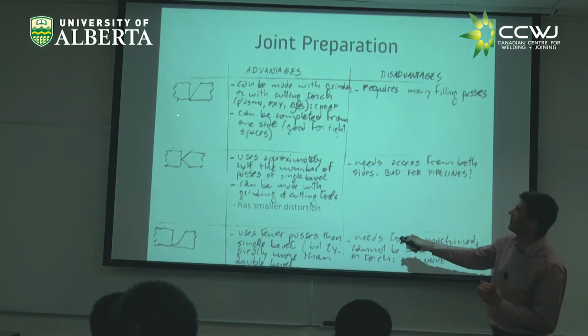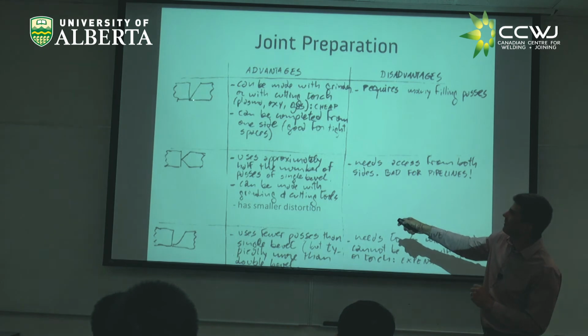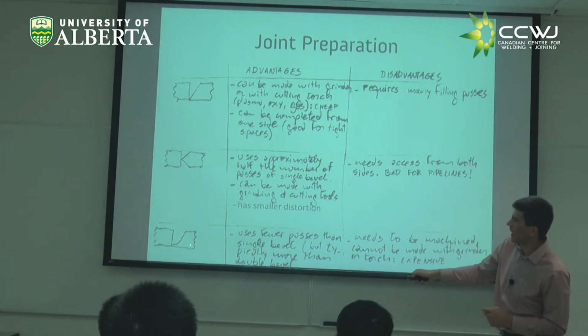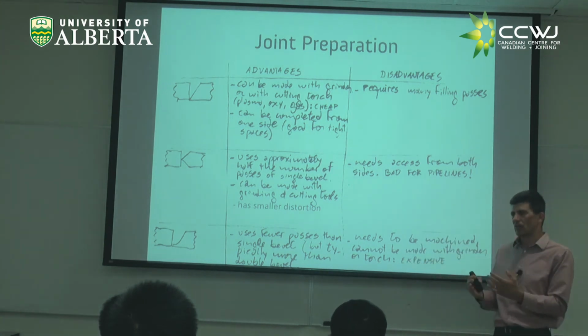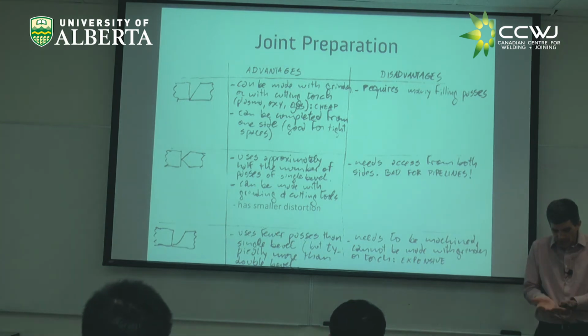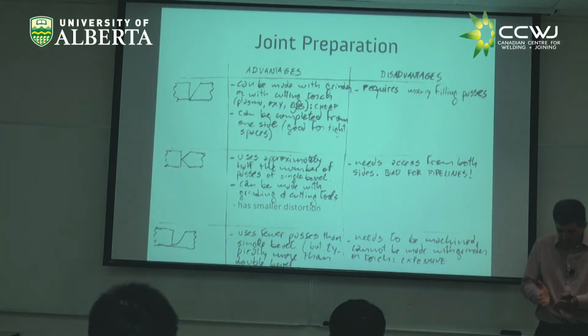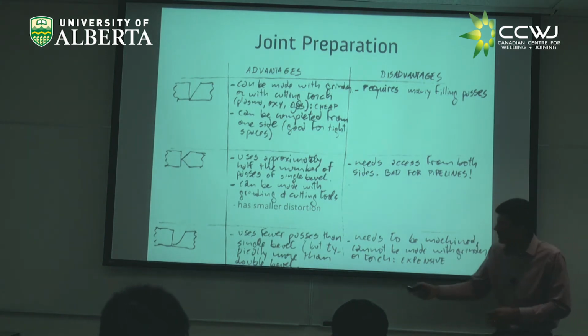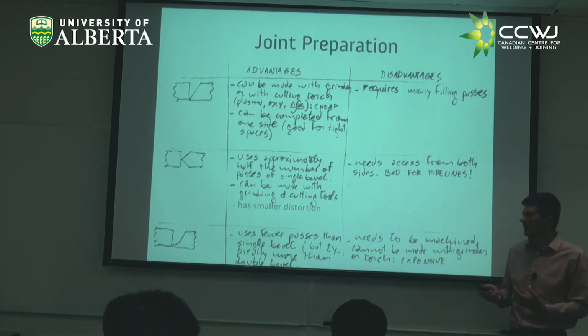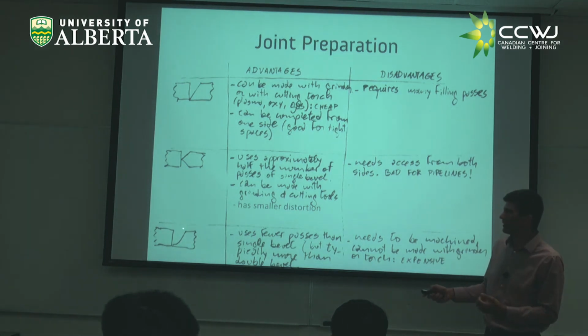the catch is that when you're committed to this, the space here might be okay, but here the space is too much, you're wasting it. So you can do this J type of bevel. In the J bevel, right, you have good enough room at the root, at the bottom, but then when it comes up, it doesn't come up opening all the way. It starts to turn, and it's not so big. So it has many advantages. What is the disadvantage? You need to machine this joint.